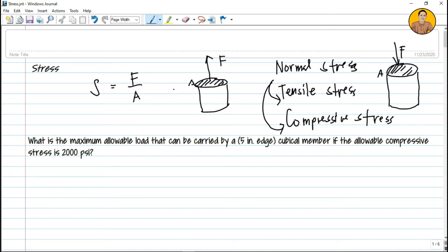Now if you are dealing with shear stress, if this is your force here, okay, this is the force. So notice that the force here is actually parallel naman siya, parallel to the force. Okay, yung area under contact. In this case, if the area is parallel to the force, inline siya sa force, this is what you call the shear stress. So the type of stress actually depends on the orientation of the area under contact. So let's solve sample problems to further explain these concepts.